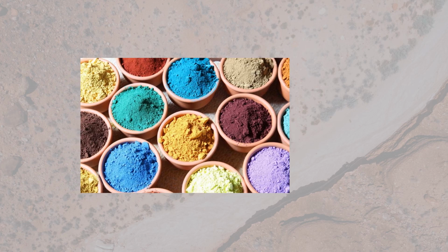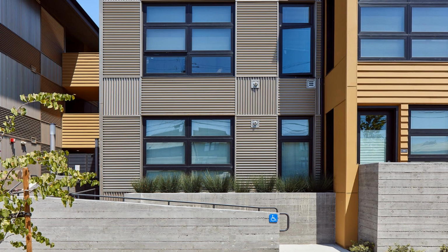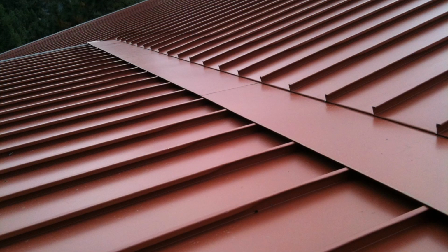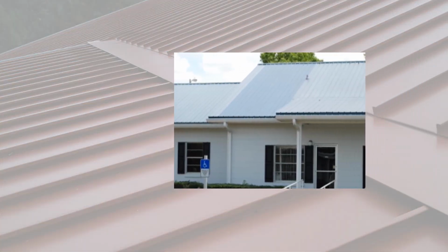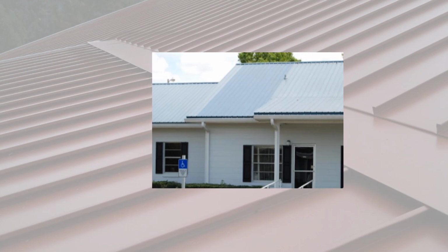Inorganic pigments are typically duller yellows, reds, greens, browns and black iron oxides. Organic pigments, by contrast, are brighter, including reds, blues, greens, violets and yellows. While they provide a cleaner, more distinctive look, organic pigments are less durable. Specifically, organic pigments fade faster when exposed to UV light. This is an important consideration when selecting colour for exterior applications.